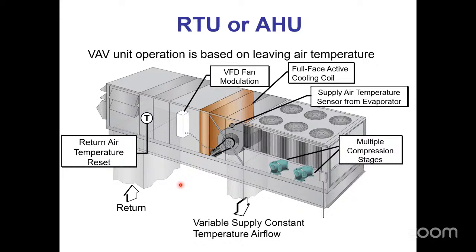Now you could have one compressor and have it be variable capacity compressor, like inverter driven or digital scroll. That would be fine, but you can't have on-off compressors. You could have 2 compressors that are recips. That's not something we do anymore today, but you might have those out there. And if it's a recip and you have unloaders on it, you could definitely get enough staging capacity that way too. They have to be electric unloaders. Pressure unloaders do not work on VAV. Has to be electric unloaders if you got a recip.